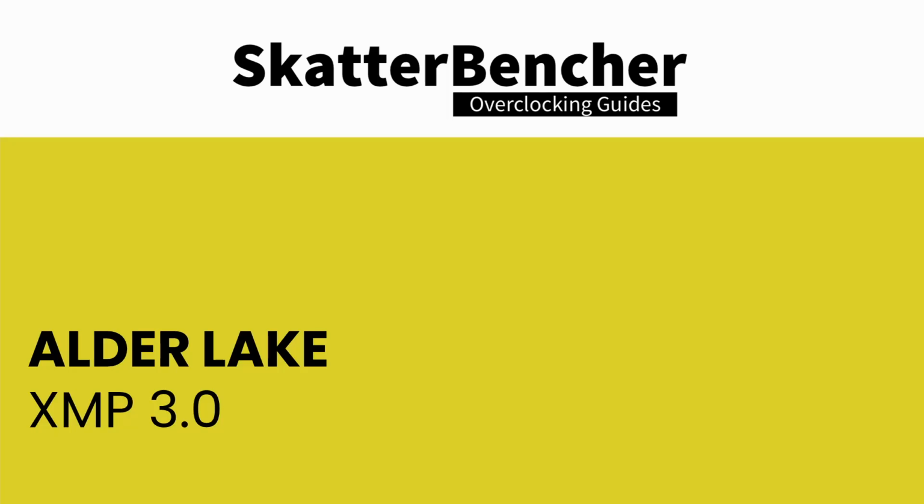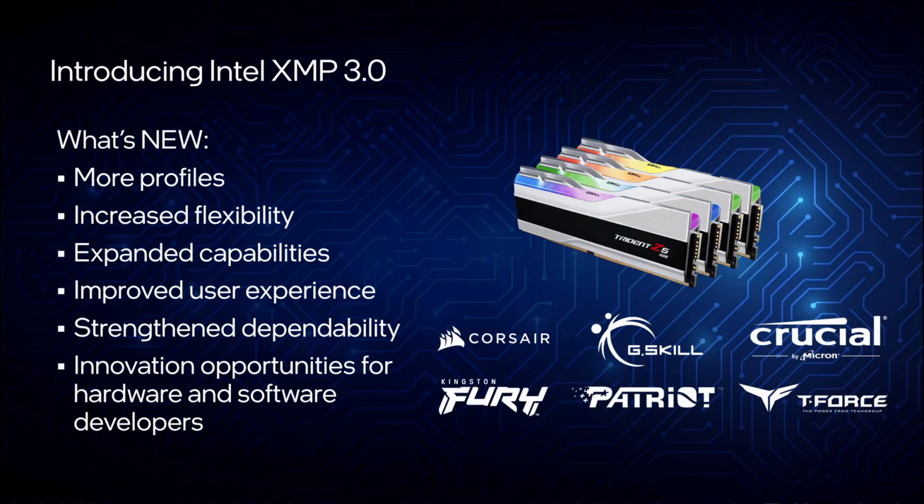Intel Extreme Memory Profile, or XMP, is an Intel technology that allows you to automatically overclock the system memory for improved system performance. It is an extension of the JEDEC standard that allows memory vendors to program higher frequency and better memory timings onto the memory sticks. Intel Extreme Memory Profile 3.0 is a new XMP standard for DDR5 memory. It is largely based on the XMP 2.0 standard for DDR4, but has additional functionality.